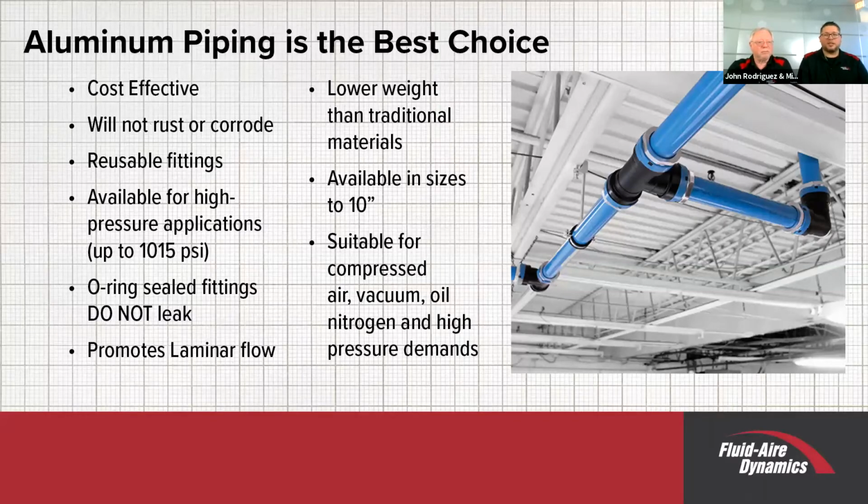You can reuse these fittings, and it does allow you to make changes on the fly. If you have to add a new unit later on, you'd be able to do that without any problem whatsoever. It's a lot easier to do that with aluminum piping than it is with any of the others. Yes, and with aluminum piping there are other manufacturers, but the advantage of this one is that it has all metal fittings. They're not plastic. And that allows it to be more stable with respect to leaks.